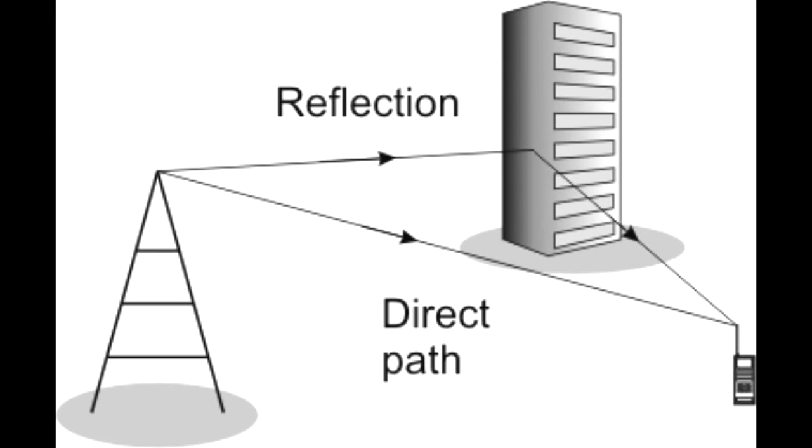What makes OFDM special? It was developed to address the problem of multipath fading. Multipath fading is when signals reach a receiver via paths of various lengths. Signals can interfere with one another and be reflected by physical obstructions, such as buildings. The receiver can also be moving, thus not creating a direct path between the transmitter and the receiver. These interferences cause distortion, delays, and degradation of network performance.